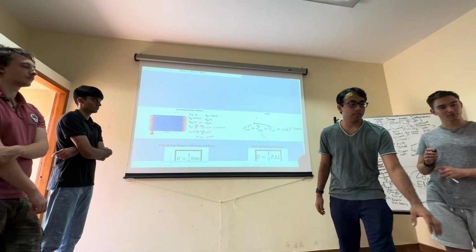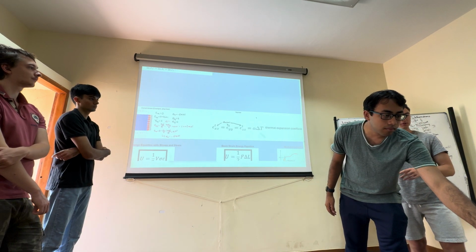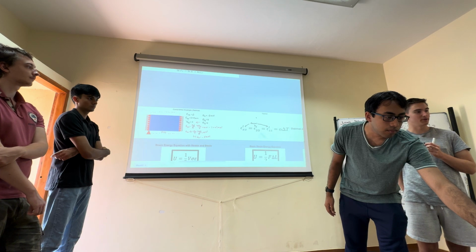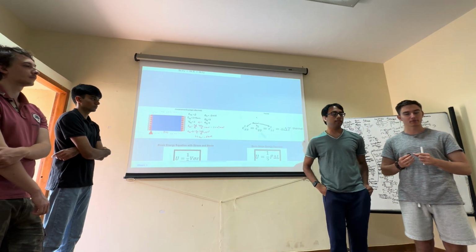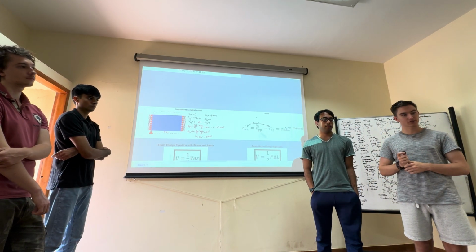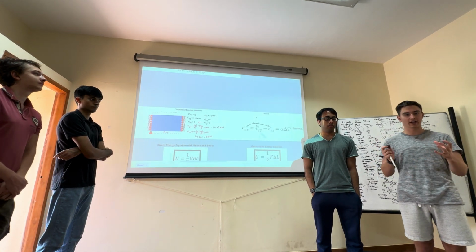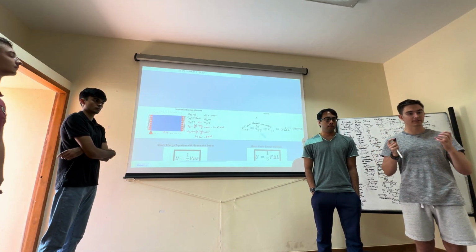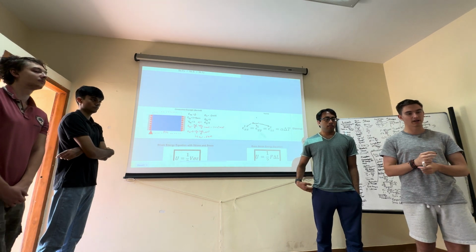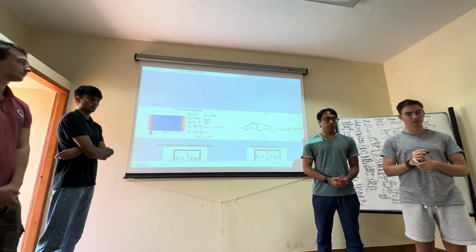This is related to what we just talked about in one of our previous homeworks, where we talked about the compatibility of composites. One of the points we made was that if you're looking at aluminum matrix composites, you had to have that compatibility because of thermal expansion, where you could have delamination of the layers because of the expansion that can occur due to the high heating you might see within some of those composites.